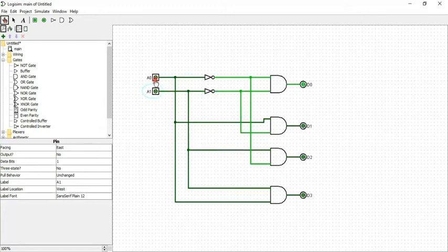A node is low value, a1 is low value, d node is 1, d1, d2, d3 are 0 value. And a node is high value, a1 is high value, the both are high value. We can see the d3 is 1 value, and d1, d2, d node are 0. Okay, this is a decoder circuit diagram. This is a 2 to 4 line decoder.